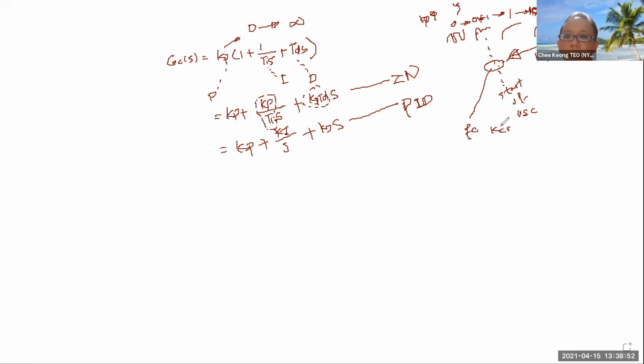He is interested in finding these because he uses them in the table, also using the critical period rather than the critical frequency. With these two, he is able to use the table and calculate your PID coefficients.